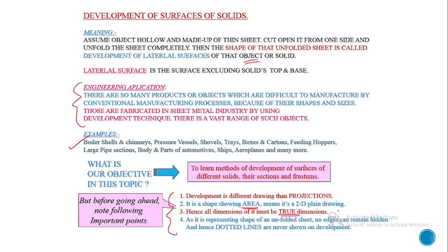That is the most important point in development of the lateral surfaces. All the dimensions must be in true length. That is the most important point.